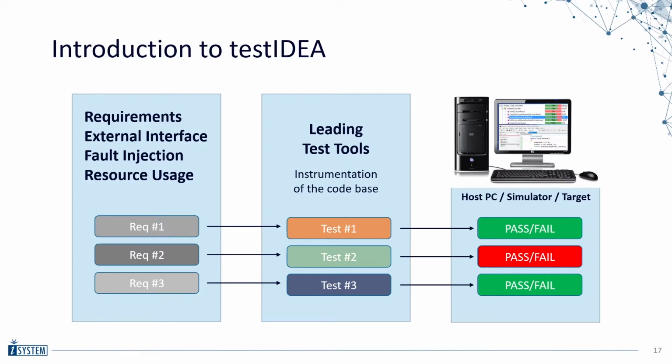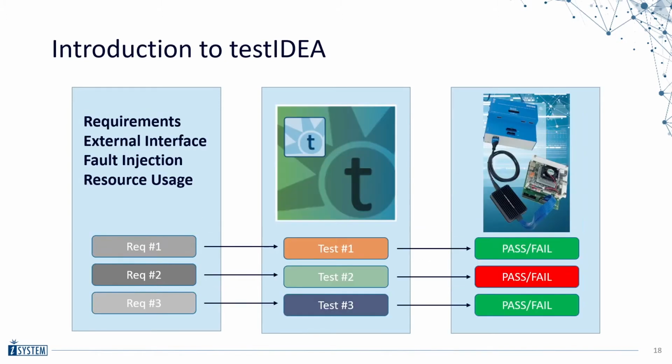What if there was a way to run automated unit, system and integration tests directly on your code base from a continuous integrated environment? That's exactly what testIDEA does. testIDEA is a test framework that can configure your target development environment into a full hardware-in-the-loop test environment. The target is configured for whatever state you are testing. Power on startup tests or failure modes. Everything you expect your controller to handle can be tested without instrumenting your code. Compiler optimizations can be enabled. All tests are executed on the target system.